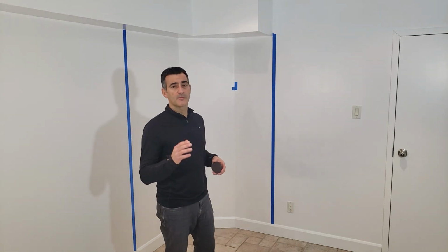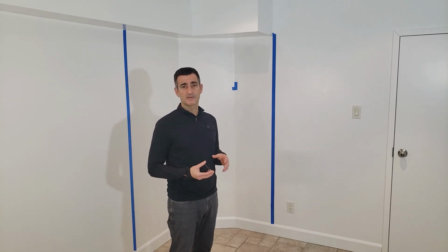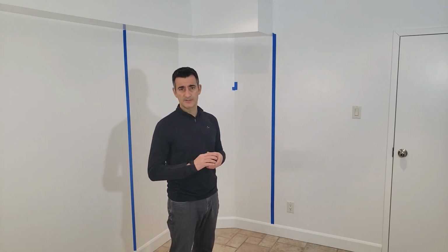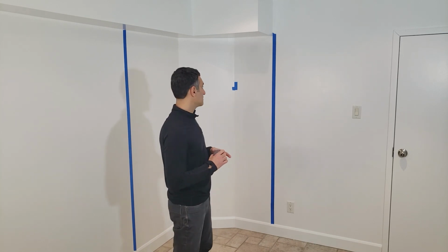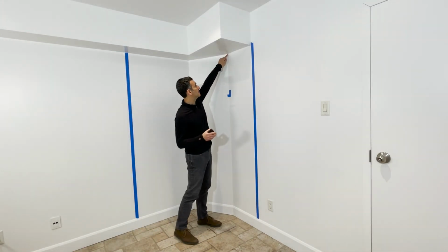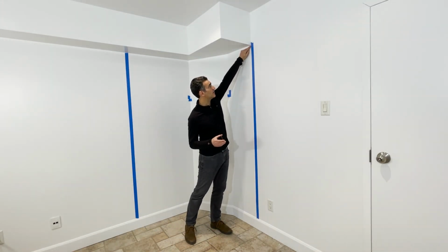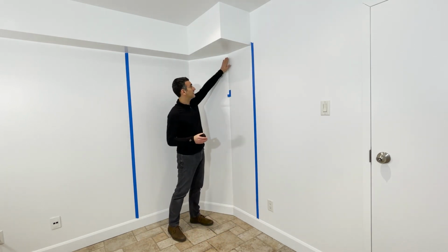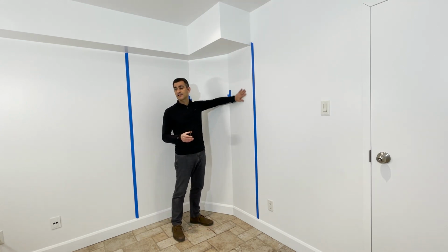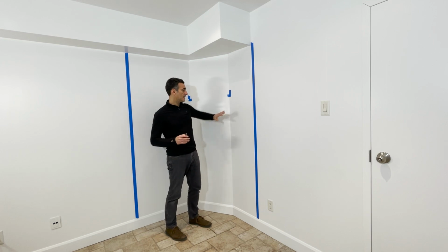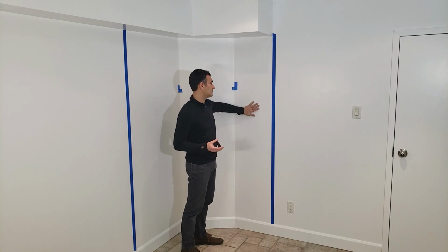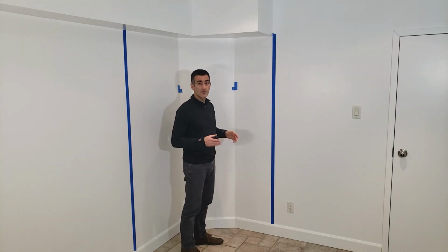Now, I'm going to be using a program called Photomodeler, which is a comprehensive photogrammetry package. It will do 3D models and make point clouds, but it also gives you the ability to manually mark points. So I can mark a point up in this corner, I can mark a point where the tape meets this corner here, I can go all the way down, hit the corner there, and basically with 4 points, I can create a plane. Of course, you have to assume that what is in between those 4 points is flat, but these walls are generally flat, and I can be okay with that.